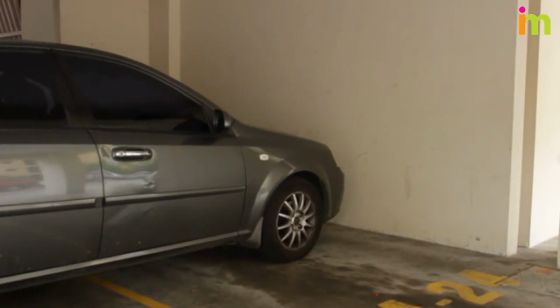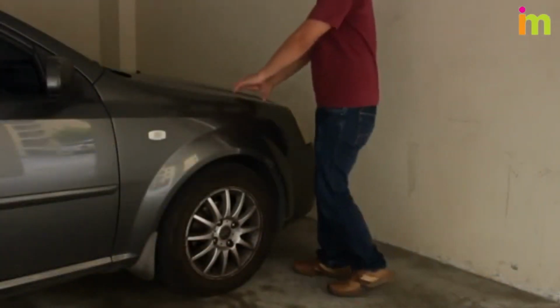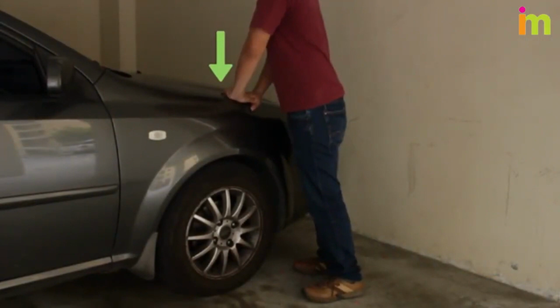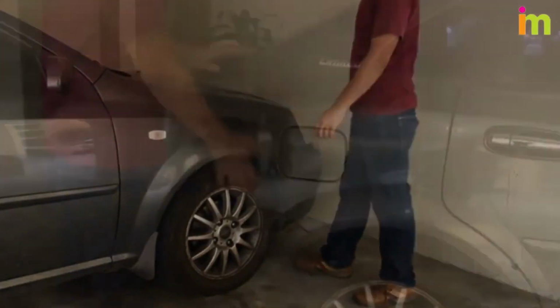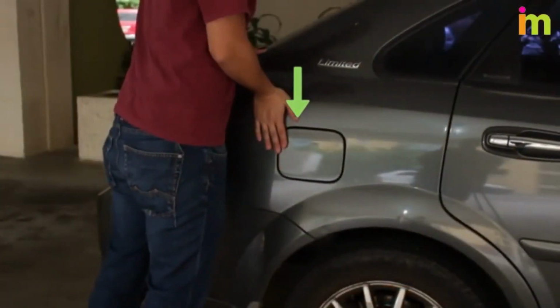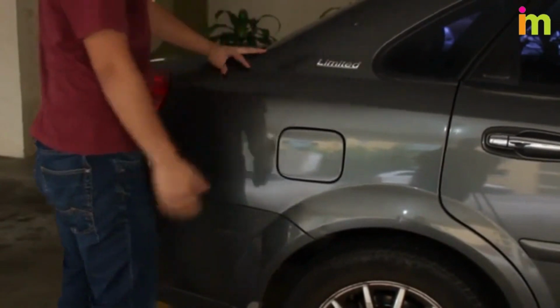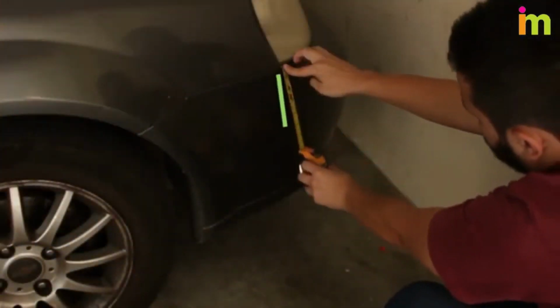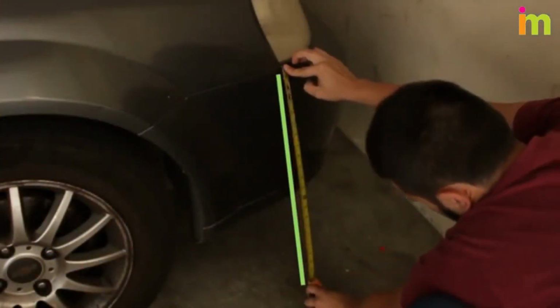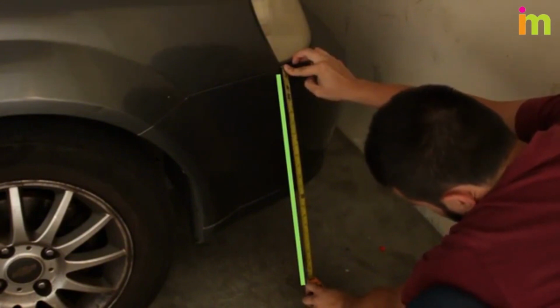Level the shocks by pushing the corners of the car down. Just go to each corner of the vehicle and firmly push down on the body to make your vehicle pop up and down a few inches. Alternatively, you can measure the distance to the ground from both headlights to ensure that the suspension itself is level.